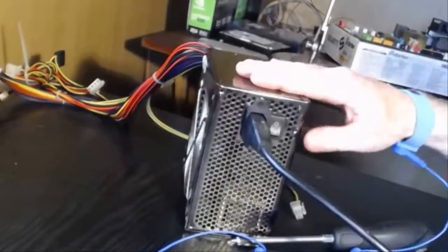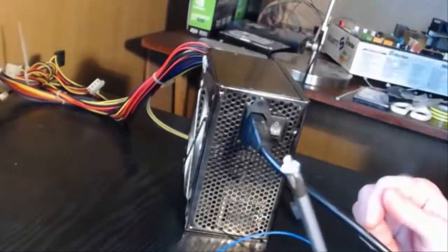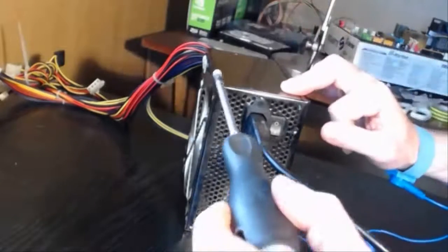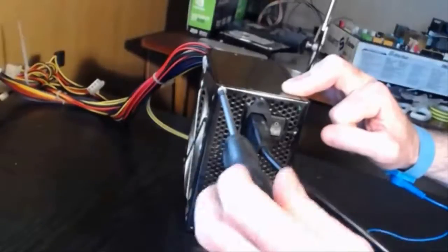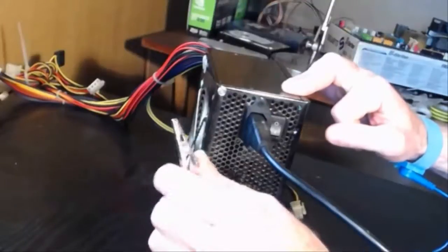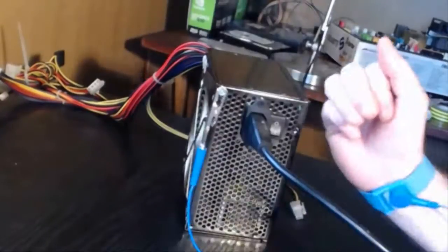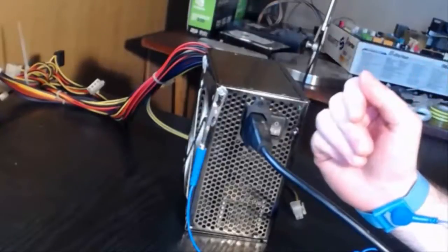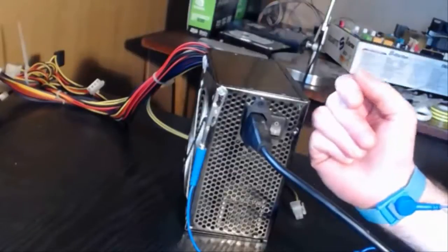And then this box is earthed, and what you do is you take a screw and just place it in one of the holes that is in for the screws, like so. And it doesn't have to be tight, and then you just get the end of your wrist strap and connect that to it, and that will connect you to ground then. Okay, so when you're handling parts now, you are grounded, so you won't have a discharge onto the component that you are working with.